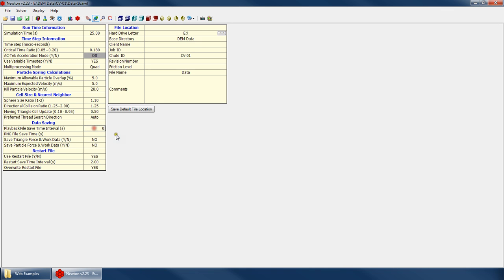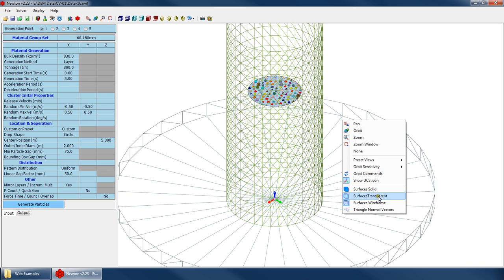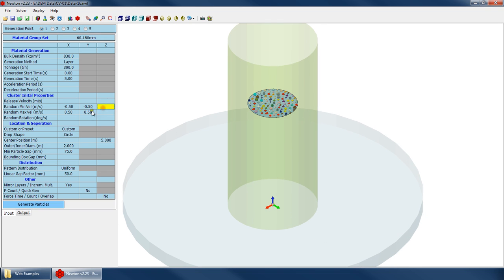I'm going to go ahead and turn this down to 0.005. And I'm going to turn that down to 0.1 so we can watch this a little bit smoother. So what if I wanted to also give it a z velocity? Well, again, we want the max to stay at 0. We don't ever want to give it a positive z velocity, but maybe I want to vary it from -1 to 0.